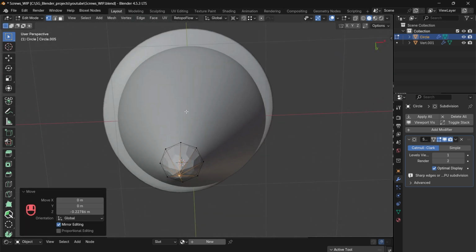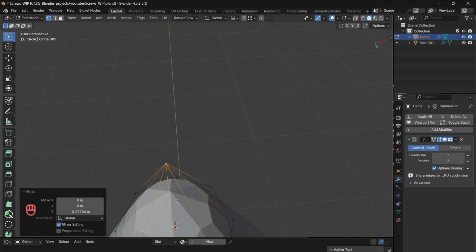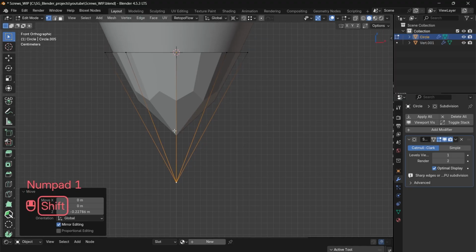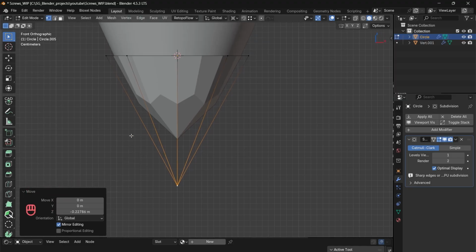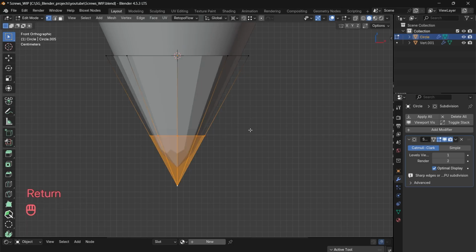Now if you do that and leave it just like that, you will see it still contains this pole with more than 4 edges, and at the beginning of the tutorial I showed you we don't do that. So I will show you this trick. Pay close attention. I use the knife tool, enable A so that it is constrained on a given line, and press C to cut through it. Now I will just cut through this.